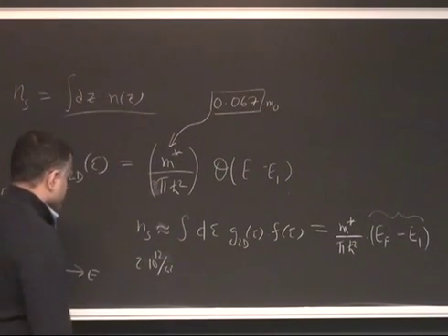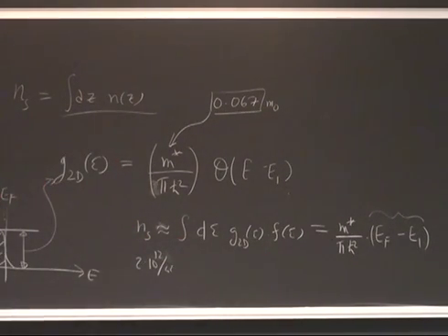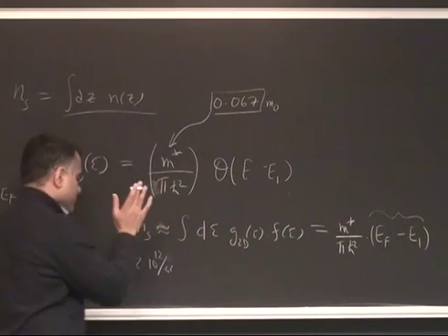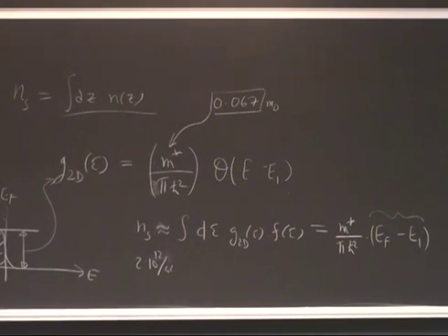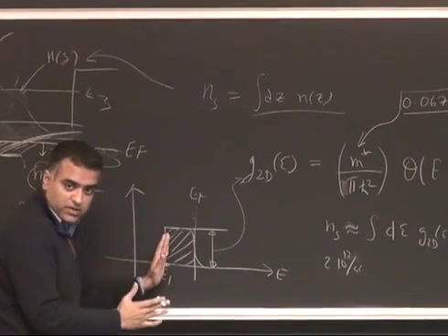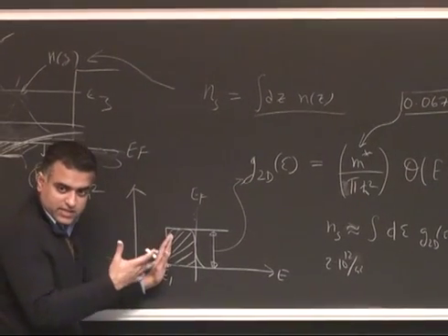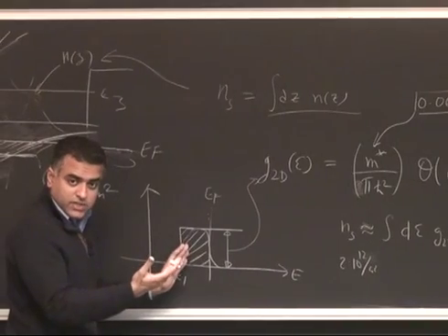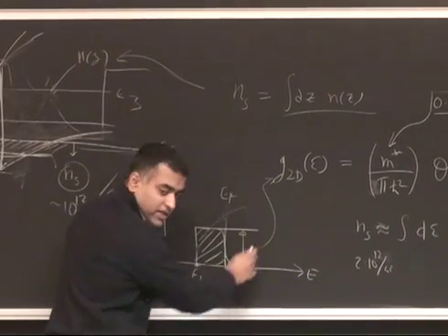Yeah, just plug those quantities in here. Okay? So what you see is the carrier density. If you are filled only to a single subband, in each subband the carrier density depends linearly on how far the Fermi level is from the minima, right? Linearly. This is not true for 3D systems, right? In a 3D system, you have a square root of energy, right?